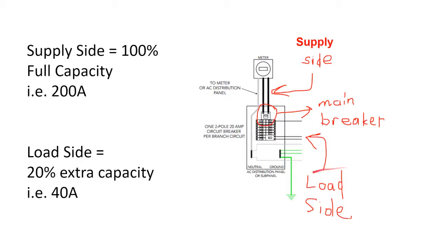Interconnection options are available either as a load side or supply side connection. The supply side connection is located between the customer meter and the main service panel. The supply side connection can equal but not exceed the rating of the electric service. That means if the site has a 200 amp service, then a 200 amp energy system can be connected to it. After all, the conductors feeding the building are rated for 200 amps.